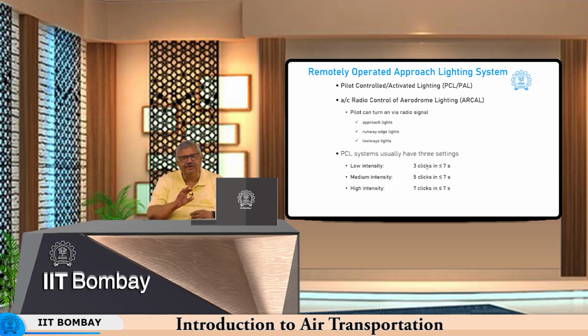The first setting is low intensity, in which there will be 3 clicks in less than 7 seconds; medium intensity, when you will have 5 clicks in less than 7 seconds; and high intensity, where there will be 1 click every second, so 7 clicks in less than or equal to 7 seconds. This system automatically turns off 15 minutes after the touchdown of the aircraft.